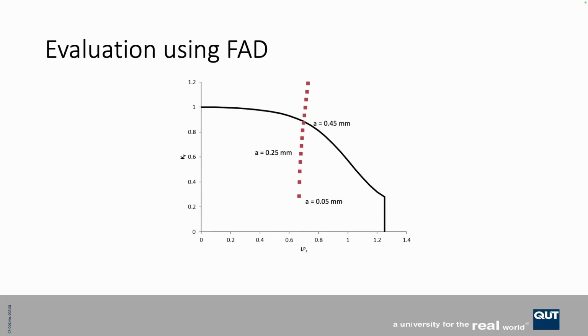And I found that the critical crack size for failure was about 0.45 of a millimeter. Now, the cracks I showed you before were up to about 0.3 of a millimeter. It seemed to me quite feasible that the worst crack there could have been 0.5 of a millimeter. And therefore, I didn't really have any evidence that this was overloaded. I thought it probably failed under normal conditions. Why it was failing by stress corrosion cracking, I don't really know at this stage.